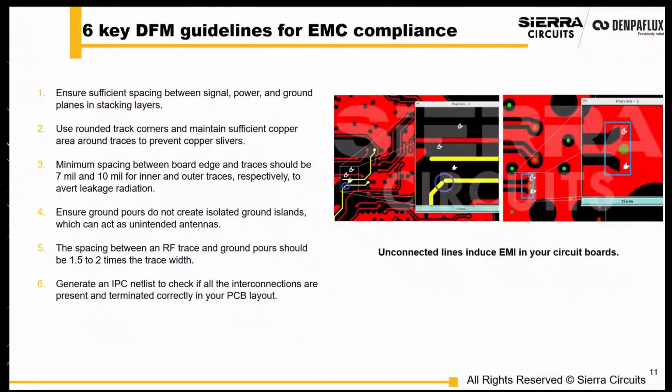When you're routing your traces, if you can have more rounded track corners, that's better. You definitely also want to avoid features that could produce slivers. When we're manufacturing boards, slivers can become an issue in the manufacturing.